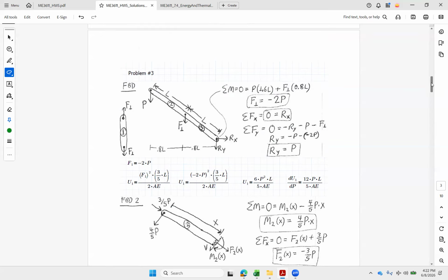So if I draw the bar first, for any axial bar, F is going to be the axial force. If I draw it positive tensile, it's going to look like that. If I draw it like this, then I pass it off just like that to the center of the beam. However I draw it on the bar, it's equal and opposite on the beam, just like we pass stuff between beam number 1 and 2 in the in-class example.